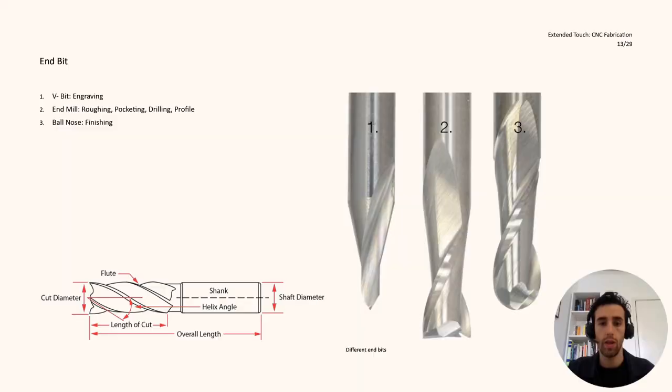The session with the Digital Fabrication Laboratory concluded with a comparison between flat end bits and bull nose cutters for smooth terrain. Step-over percentages were explored and how they affect surface resolution. Surface finish comparison: side-by-side footage of roughing and finishing passes illustrated how incremental step-over adjustments can refine the surface of the models. Armed with this knowledge, student teams presented evolving designs to fabrication staff, receiving feedback on design optimization.